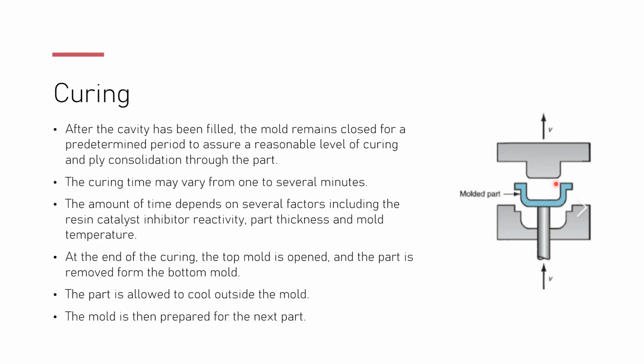Curing, we're going to set it. After shaping it, after the cavity has been filled, the mold remains closed for a time. It depends on what you're making. Even though it's so easy to write it here, you have to pay attention when you're actually making it, to assure a reasonable level of curing. Of course, you will always have a standard deviation, plus or minus, with temperatures going up and down. Lower curing implies less consolidation through the part.